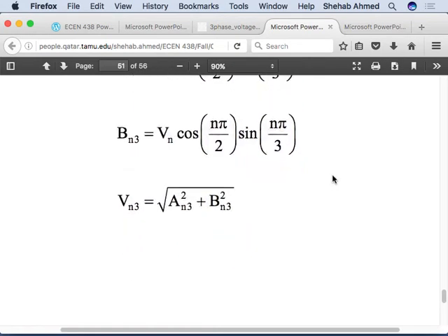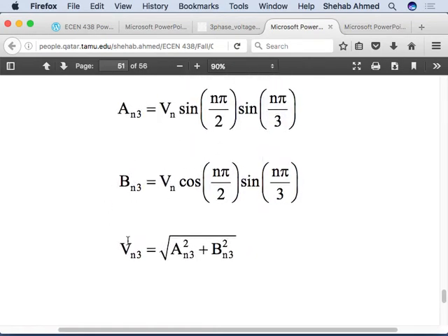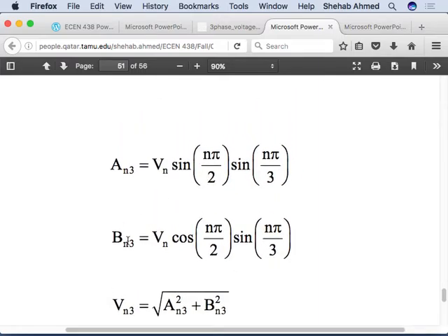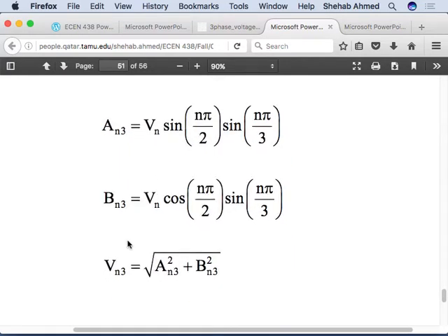Yeah. And these numbers tell you the values of the various harmonics that you're going to put in the system when you use a three-phase inverter switching using a six-step mode, or using sinusoidal PWM mode, or other types of modulation. Right? This is where you get the numbers that you take and calculate and plug into these harmonic studies.